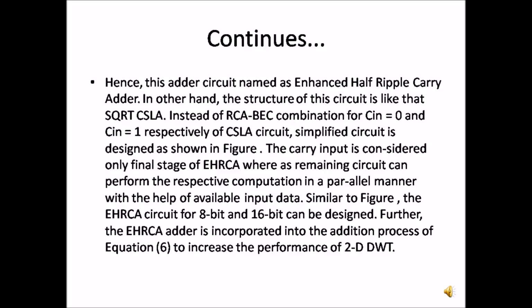On the other hand, the structure of this circuit is like SQRT CSLA. Instead of the RCA and BEC combination for carry input 0 and carry input 1 respectively as in the CSLA circuit, a simplified circuit is designed as shown in the figure. The carry input is considered only for the final stage of EHRCA, whereas the remaining circuit can perform the respective computation in a parallel manner with the help of available input data. Similar to the figure, the EHRCA for 8-bit and 16-bit can be developed. Further, the EHRCA adder is incorporated into the addition process in order to increase the performance of 2D DWT.